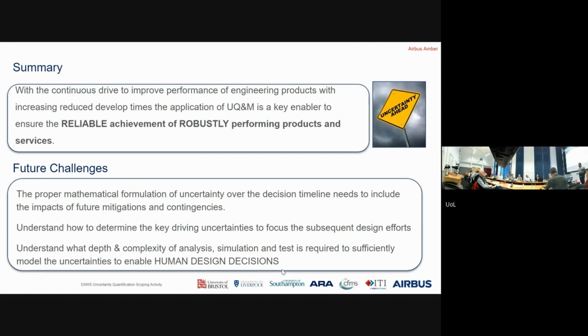And how to understand the key driving uncertainties and where to focus the subsequent efforts. You can't focus your efforts on everything. So a lot of what we do at Airbus is try to find the things that are driving your design. You do sensitivity analysis, you find the things that are most important, and you look to understand those. But you may potentially be missing ones that suddenly pop up later that you haven't considered.